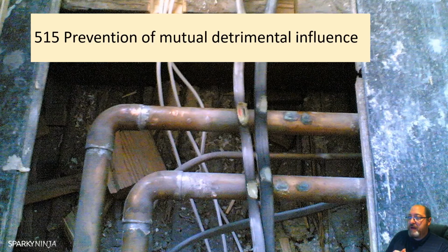Or it could be where you have an issue with regards to a non-electrical system. A common example I have seen a few times is extraction fans. When you specify an extraction fan and you don't consider the amount of air that it is actually moving in litres per second, sometimes you can buy one that's excessive, and you may end up spilling gases.